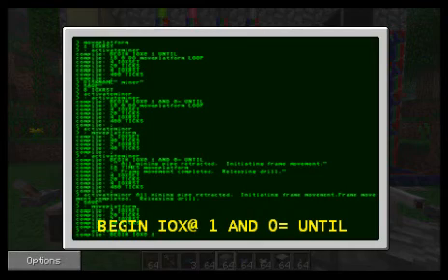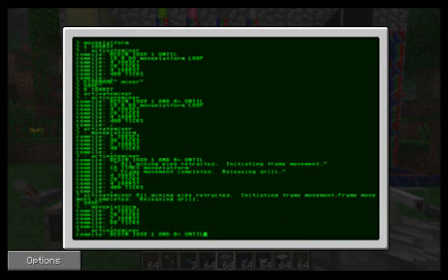IO expander @ is reading a value from the IO expander, and then you specify which one, and 0 equals. So it's going to wait for that wire to be off. So it'll be sitting there on, and when it's off, then it will activate whatever comes next. So okay, until, so it sits there and waits until that happens, pretty much.